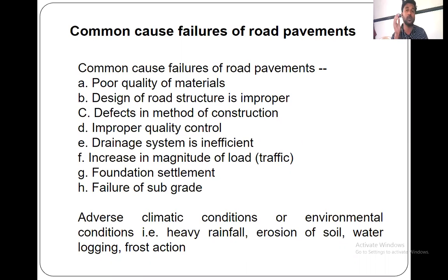Also, if proper drainage is not there, proper camber is not maintained, or the slope to carry the water into the drain is not maintained, what will happen? Water will stay there only. So due to the transportation of heavy loads, and the water being there, cracks will develop. What will the water do? It will try to loosen the bond between the different materials, the aggregate and binder material.